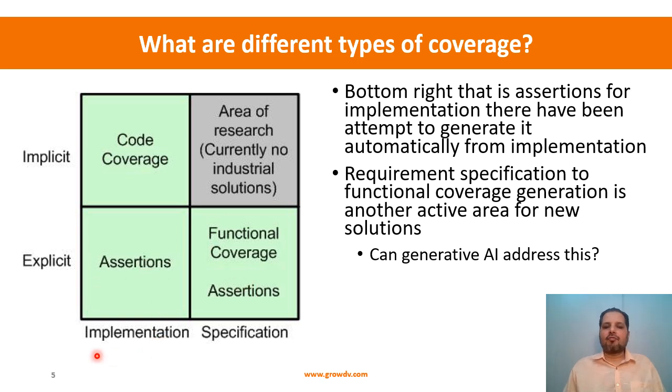So one is that if you have an implementation, that is you have a microarchitecture or design in the form of an RTL, and you want to cover certain microarchitectural aspects, like for example in a FIFO we were saying, whether the FIFO has become full or not, for example, right? Or both the push and pop are happening at the same time. Those might be a microarchitectural consideration.